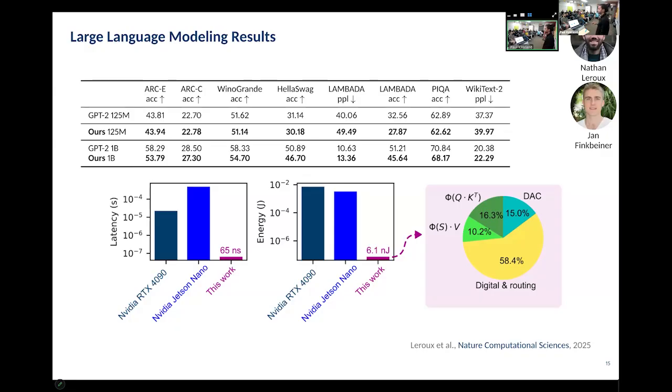I should say here that if you do projections of what the chip size would be, I don't have the numbers in my head now, but unless you do 3D, this is way too big a chip, right? Because you need to store the whole KV caches, 1 billion bytes worth of KV caches on gain cells. That's a lot of space. You have to go 3D, and use really small cells, gain cells with all these FETs in them.